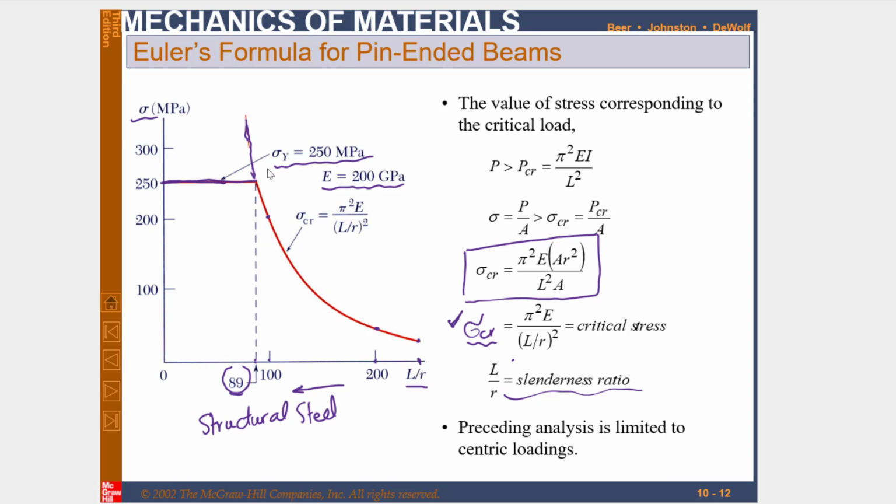It means the critical stress, or the strength of the structure regarding stability, is increasing, but as it exceeds the yield strength, the system will not buckle, or the system will be stable, but due to this compressive load, the system may yield. Clear? So the system may fail due to the yielding.